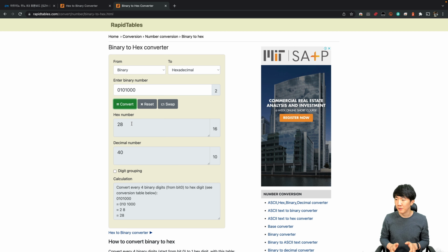The reason the I2C address is 7 bits is that when viewed in terms of 1 byte, only the first 7 bits actually correspond to the address, while the last bit is used to distinguish between writing and reading, which is why 7 bits are used.